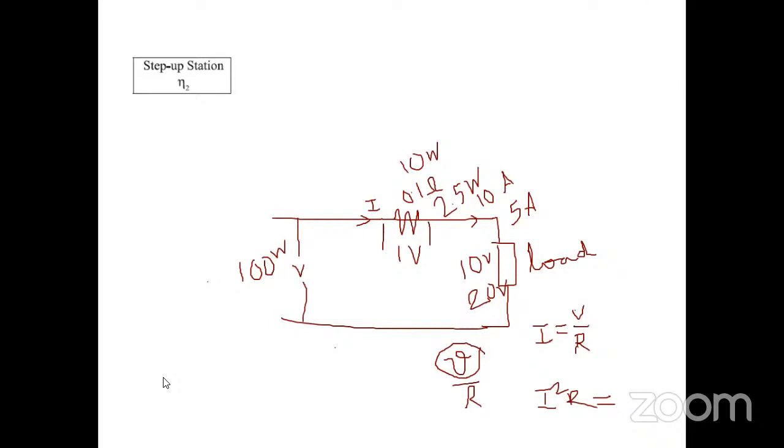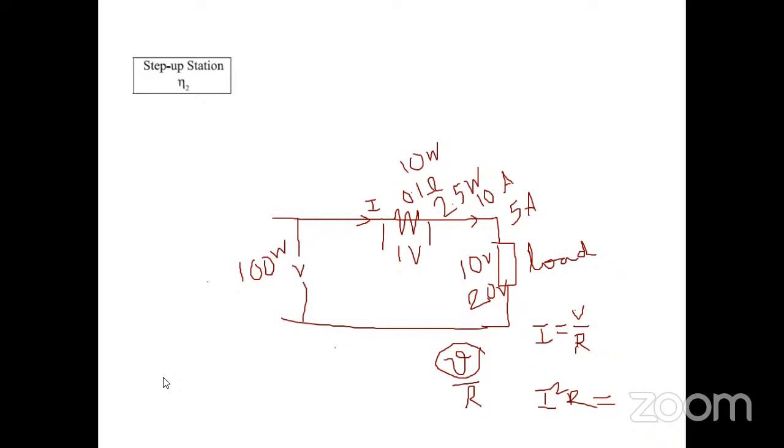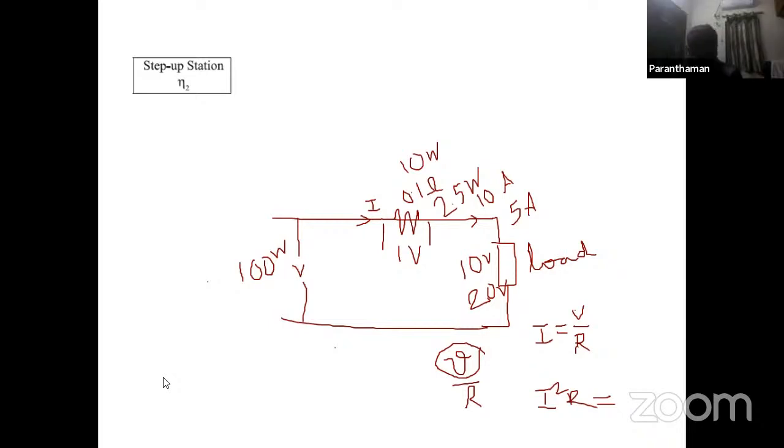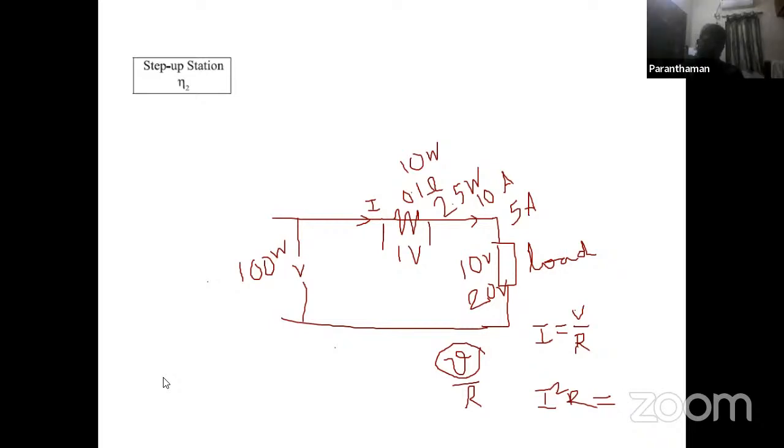We need only 700 grams of coal to generate 1 unit, so we have to multiply it with 0.7 or something. So for generating 1 unit, we'll be using around 2,450 kilocalories. You have the calculator with you, right? 2,450.